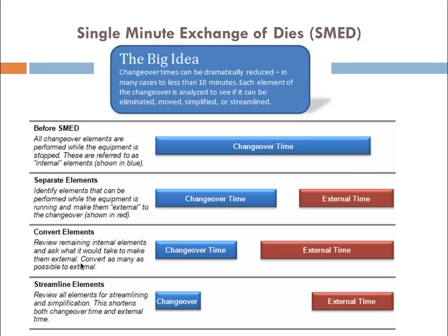Before SMED, all changeover elements are performed while the equipment is stopped. These are termed as internal elements. We need to separate these elements into internal elements and external elements. And after converting such elements, we need to review the remaining internal elements and ask what it would take to make them external. And then try to streamline elements. This shortens both changeover time as well as the external time.